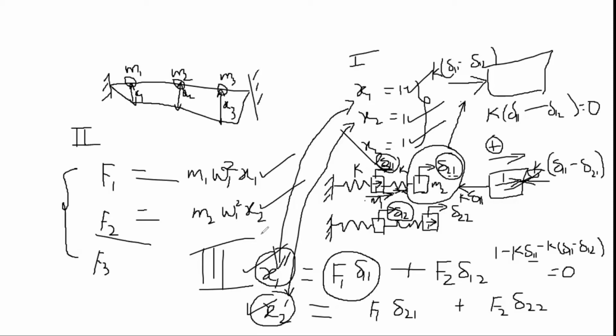Okay, so if these values are not matching, then we'll have to start a new iteration by assuming the new values of the assumed deflection curve as the calculated values. Then, with the same steps, we again find the inertial forces with the new values of deflection, and calculate the new values x2 double dash.